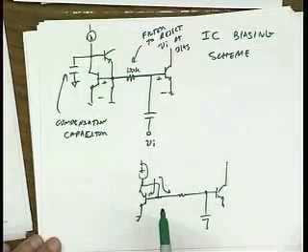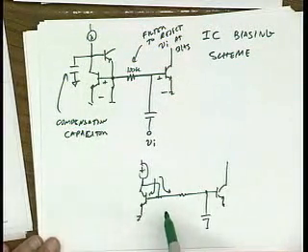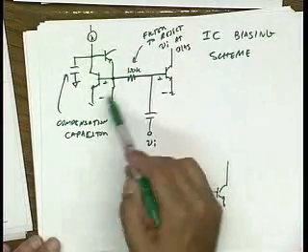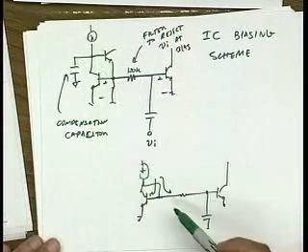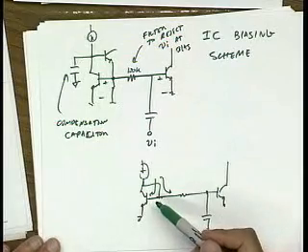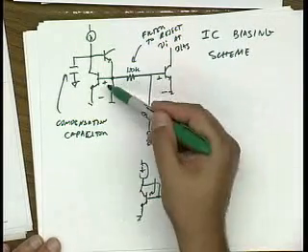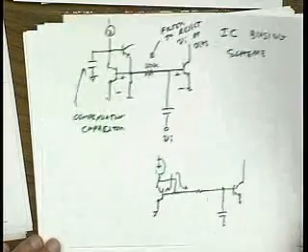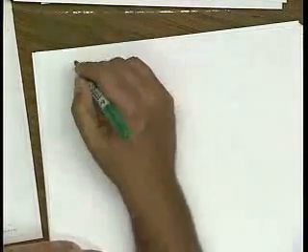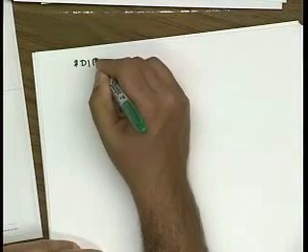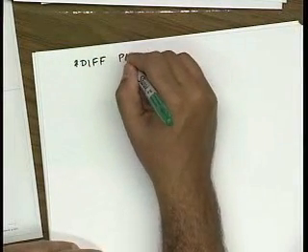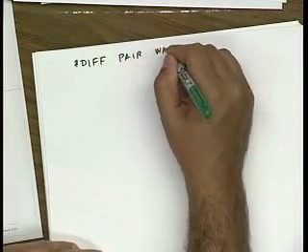And in CMOS technology, that's not an issue. But the other nice thing about this shunt feedback is it lowers the input impedance. Here, the input impedance is about 1 over GM, right? Here, it's much lower. Okay. Well, the same approach that we use for the single device can also be applied to a differential pair.